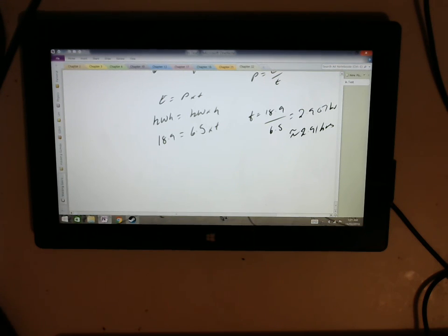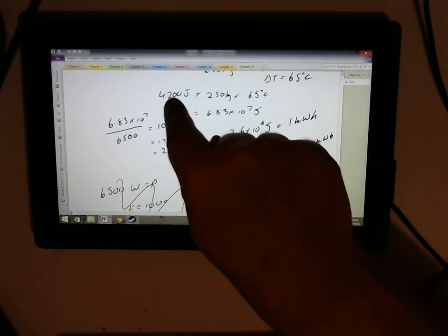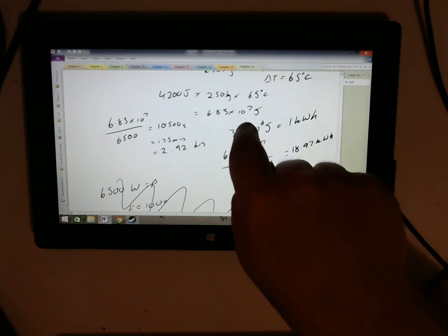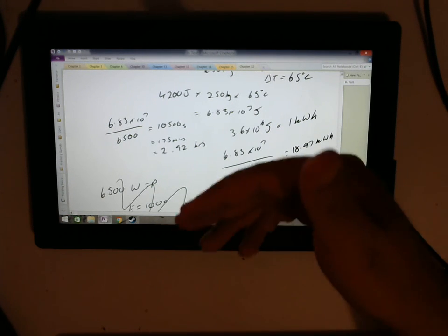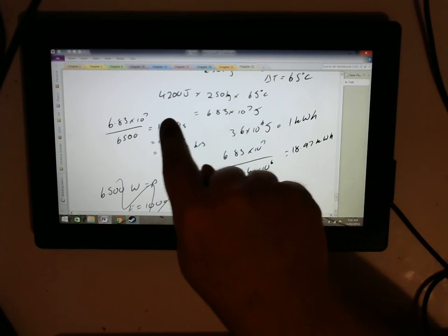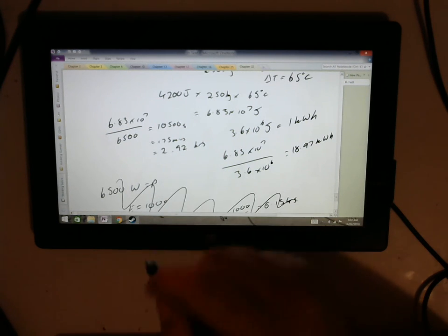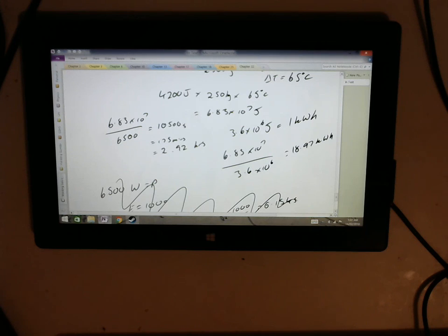So it looks like to work out kilowatt hours, what you need to do is take the kilowatts, pardon me, work out how many hours it would actually take to gain the energy you're interested in, and we've done that just using that energy formula from the information we were provided about the water, how much mass there was, and how hot we want to make it. So that gave us the total energy. We can use these two things to work out the time it would take, and then if we multiply these two together, we end up getting the value in kilowatt hours.